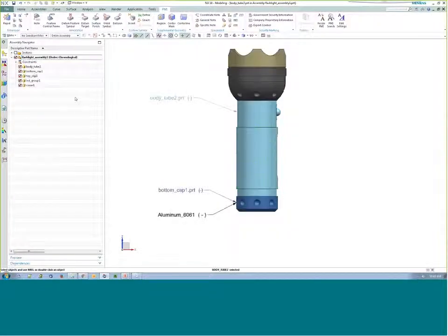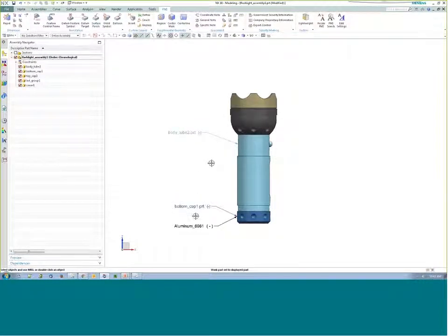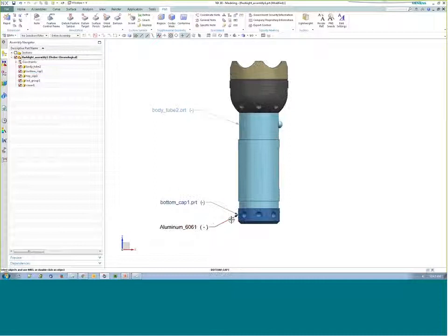And what they are is, from the assembly level, kind of a window into the individual parts, and we're filtering what we want to see for each model view. So they're not separate entities. There is a way that you can also make copies of PMI and bring those up to the assembly level, and that's the PMI Wave Linker. If you're familiar with wave linking, PMI Wave Linker is the same process. It brings an associative copy from a component level up to the top level of an assembly.